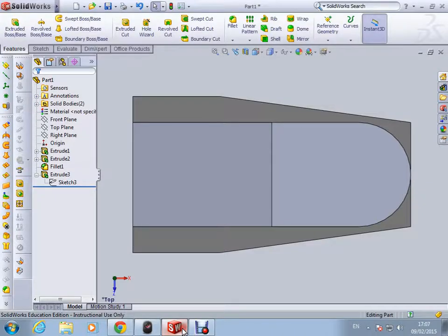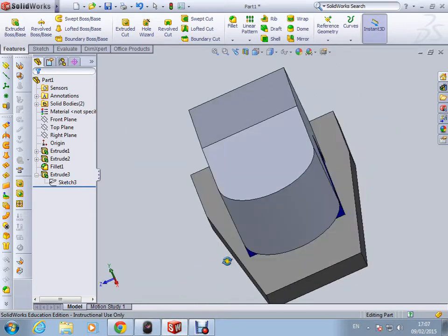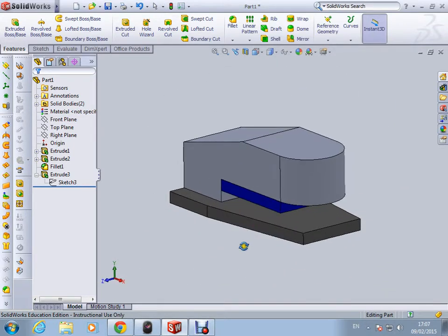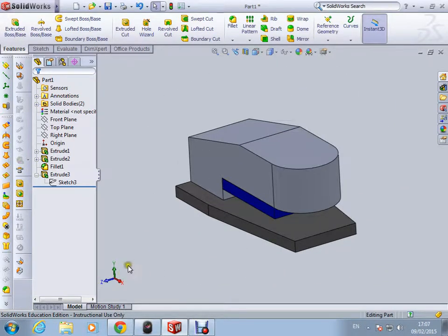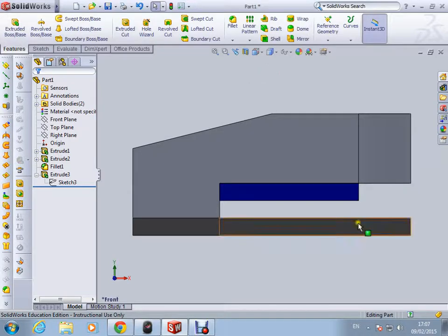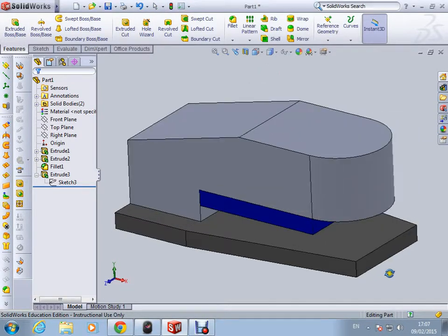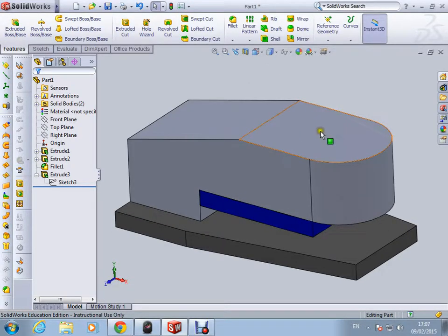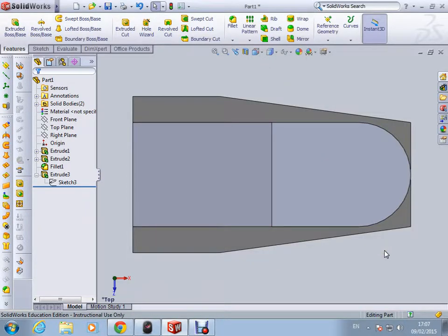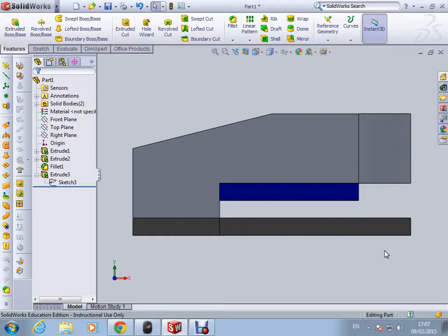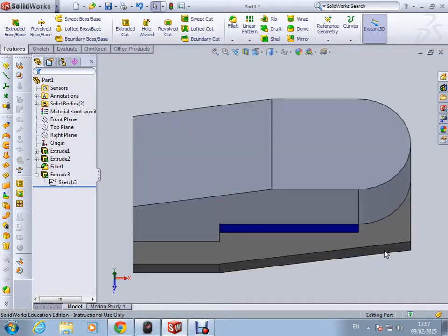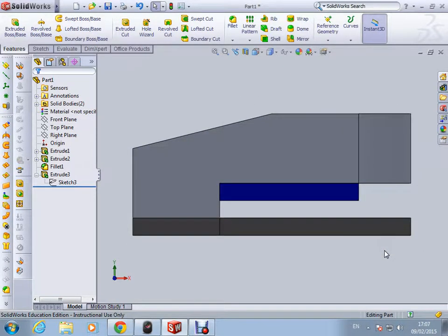So, just looking at a 3D view of our model for a second. Our elevation asks us to look in from where the cursor on the mouse is over on this side, direction of arrow A. So looking in at that, our view will look something like this. The plan, the second part of the question, is looking down on top. Look down on top of the object, our view will look something like this. Going between the two, from plan to elevation, that's what our view should look like.